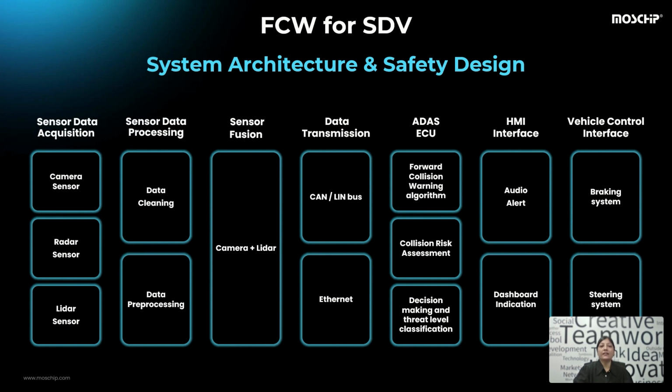Cameras, radar, and LiDAR watch the same road from different angles, while dual channel CAN and Ethernet move the bits. Think about a winter night when the snow starts coming hard. LiDAR signals bounce off falling snow, which causes false or noisy reflections. The controller spots confidence dropping and flags the sensor as unreliable.